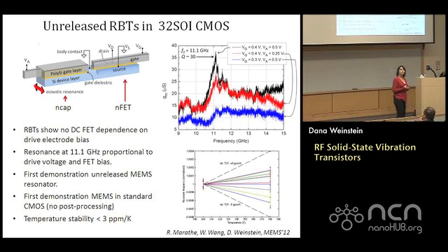You can actually use oxide, silicon dioxide, to form a passive temperature compensation, leveraging the fact that silicon and silicon dioxide have opposite temperature coefficients of Young's modulus. So with the right balance of these materials, you can cancel out the effect from silicon with the effect from oxide and get a very thermally stable resonator. Well, we get that for free.